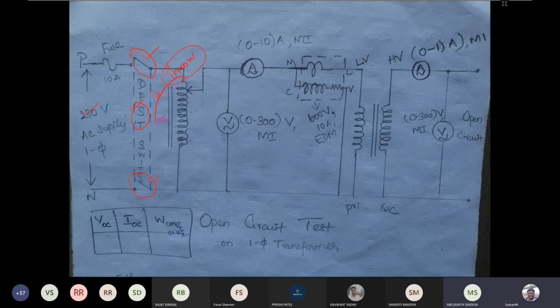So this is the auto transformer. This auto transformer is helpful to change the voltage from 0 to maximum or rated. This is the initial condition. This diagram shows that your transformer should be at 0 volt at the initial condition.